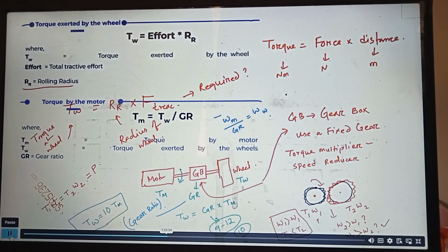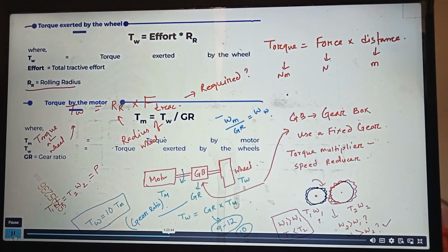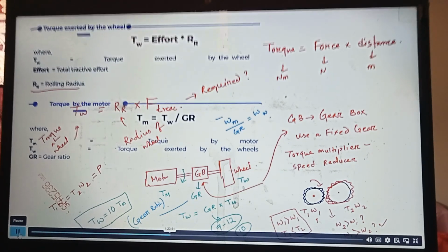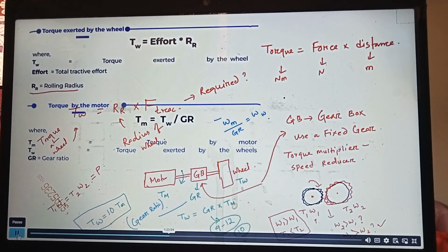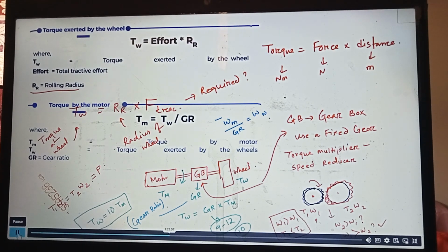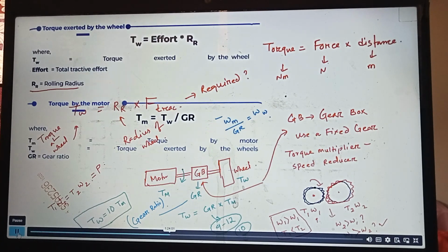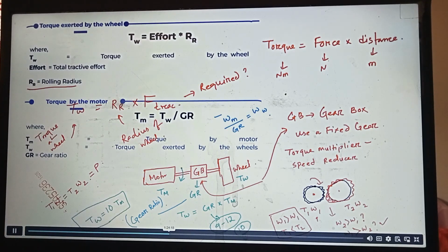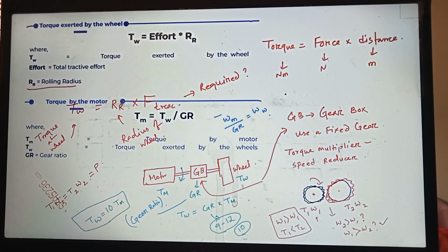The main problem from high speed comes to your mechanical arrangement. As yesterday also some of you mentioned, between stator and rotor we have a very small gap. How do you manage those gaps? As I told you, using some bearings. We should connect both rotor and stator, at the same time maintaining some air gap. Now, getting a high speed bearing is also a challenge. Let's say you want a bearing of 20,000 RPM at the power level of 100 kilowatt, 200 kilowatt. It's not an easy job. It has to offer both high speed and high power, high torque. So generally, the speed limitation comes from mechanical and design constraints, whereas torque limitation comes from the current rating as well as your magnet requirement.